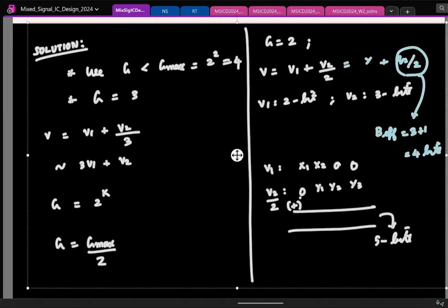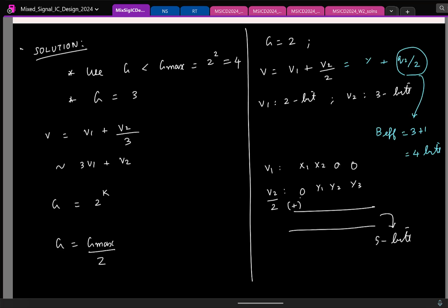Again, this is very similar to the redundancy case we saw in SAR ADC, right? Because in a SAR also we saw, to correct for any errors you make in the first comparison, you do redundant comparisons. So an n-bit SAR can give more than n bits at the output, but the effective resolution is still n. So this is something similar, so we also call this redundancy.